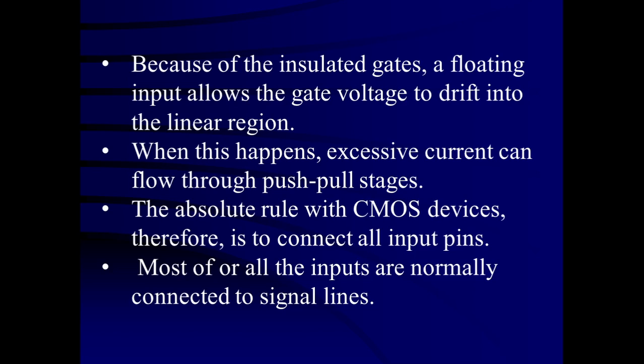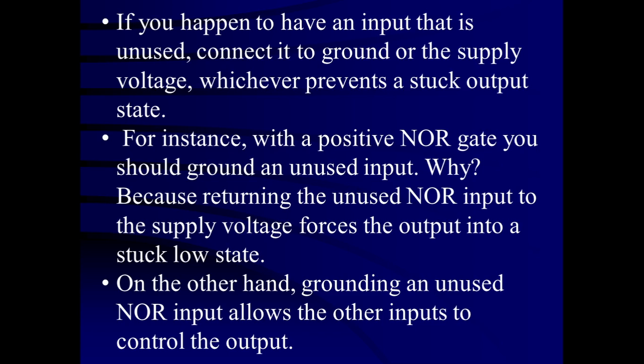Either they should be connected to the signal lines, or to the supply voltage, that is plus VCC, or to ground, which will not cause any false or stuck output.